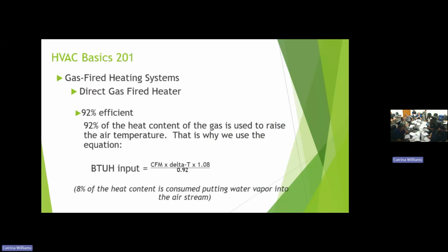So when they have the switch on those that they order that's extra, is that part of the controls? They switch it off as soon as it's too much gas going through? High limit switches, yes. If it goes into high temperature, there's one that will shut it off. We also have switches that turn it off if you have too high or too low of airflow, because both of those factors will affect the burn and may affect your results. If the airflow is too low, too high, or the temperature reaches too much, it'll shut down for safety.